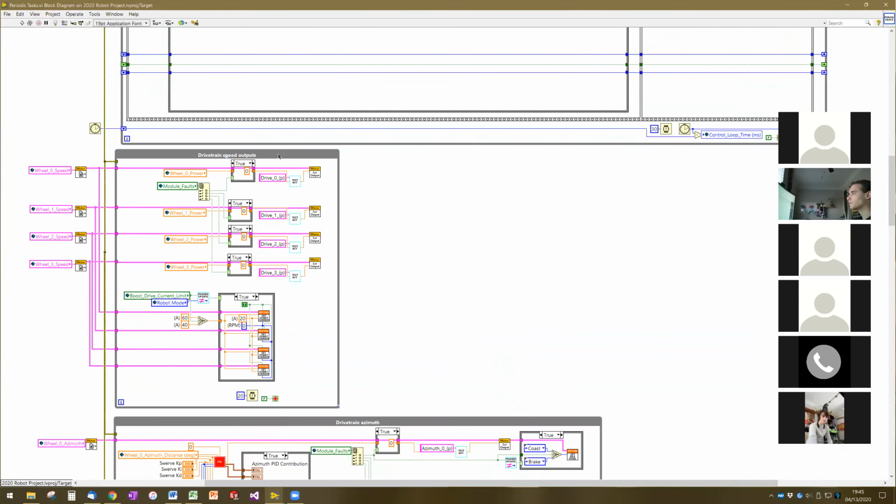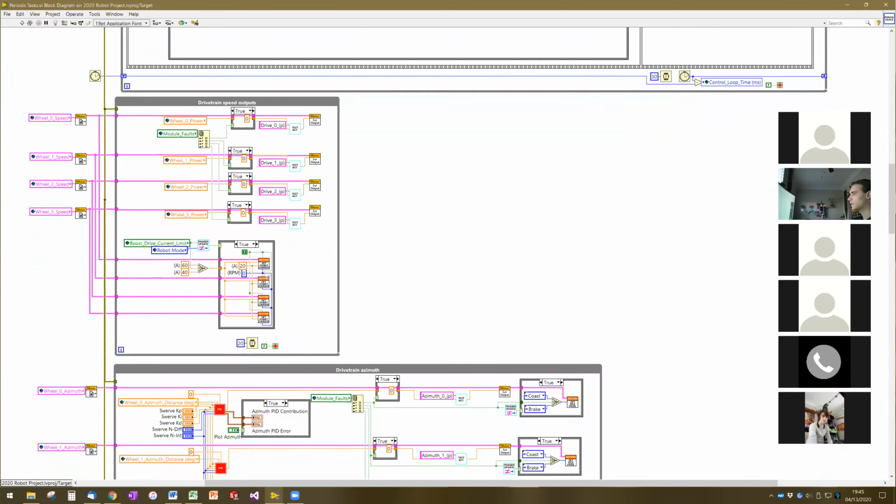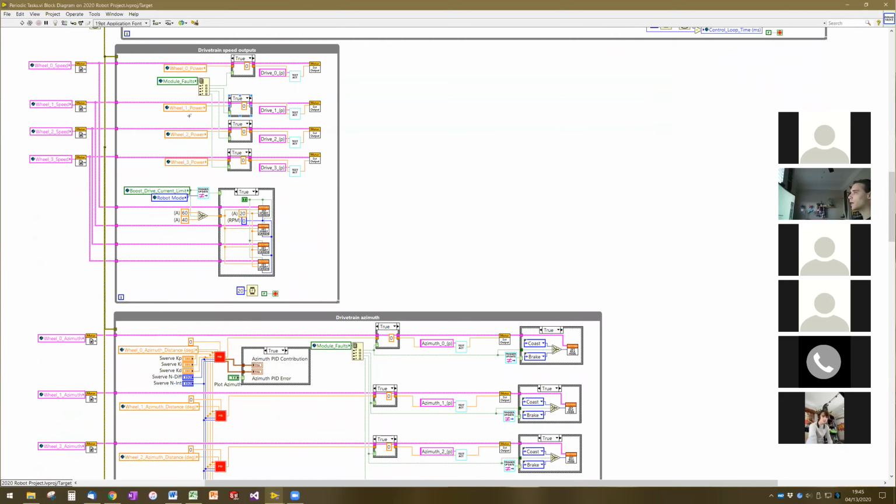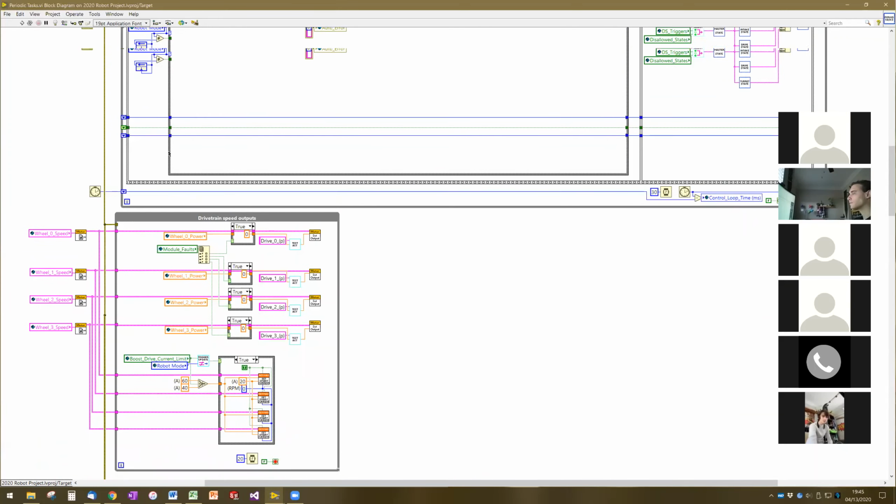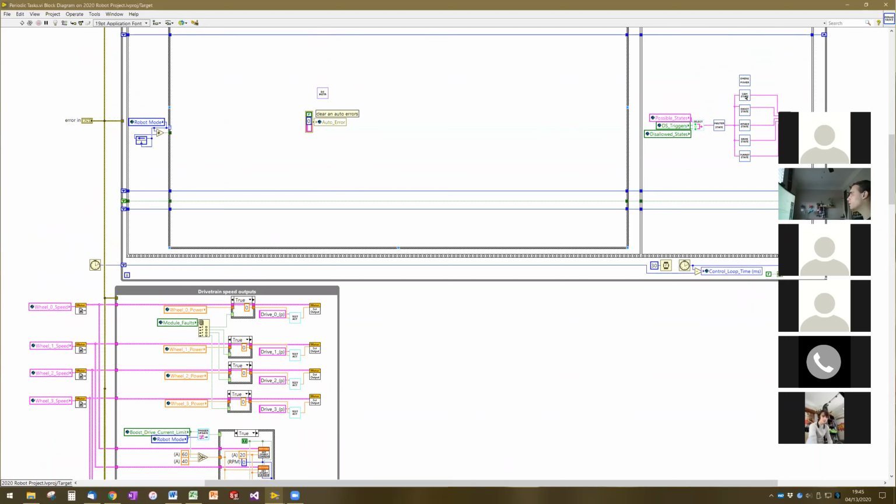So we've got the drivetrain speed motors, the motors that are spinning the wheels on the drivetrain, that's one subsystem. One thing I'd like to point out is basically the output of all of the state controllers are global variables that are sort of the very last, raw value that you are going to send to the actuator.